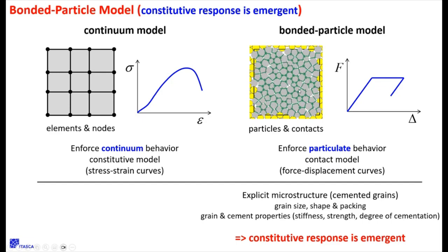So what people will typically then do is use a continuum model with some kind of constitutive model to actually do those analyses. But computer power keeps getting more and more powerful. We can do bigger models now. And so we're beginning to do boundary value problems with bonded particle systems directly. Or we do excavation problems, but in the region of interest where the damage might happen around the excavation, we put in a bonded system.